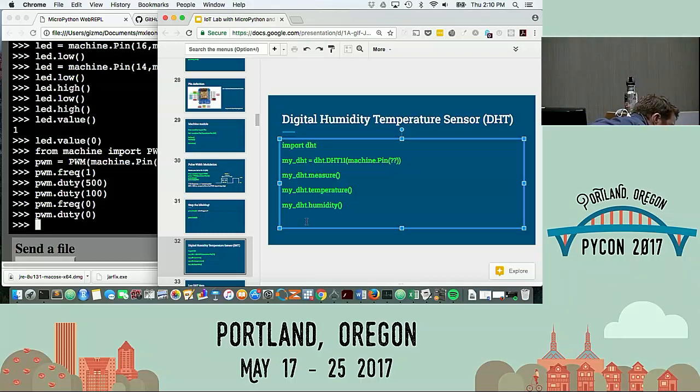Okay, so over here, if you look for GPIO 14, that will tell you that is D5. So that's the pin on this board that you would have to change to. Right now it's on D0, because that's where the wire is going into the board. The green one, that's pin D0. You'd have to pull this wire out and stick it into the hole above it. D5 is the one just above it.